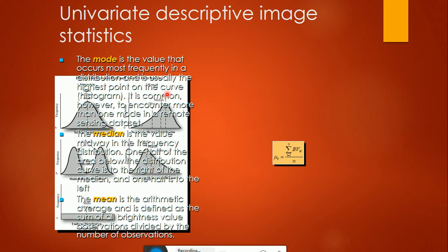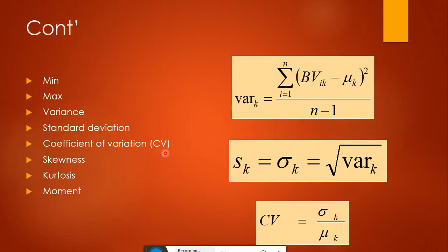These are the radiometric correction, before correction and after correction. The figure shows a typical system error which results in missing or defective data along a scan line. Bad values in a line are normally corrected by replacing the line with the pixel values in the line above or below, or with the average of the two. Speckle noise removal, before and after, you can see.